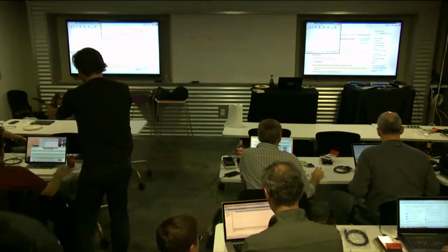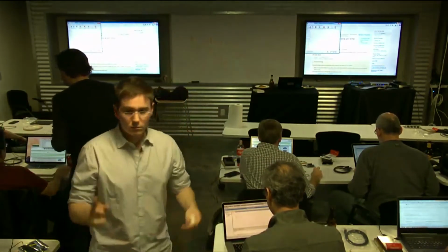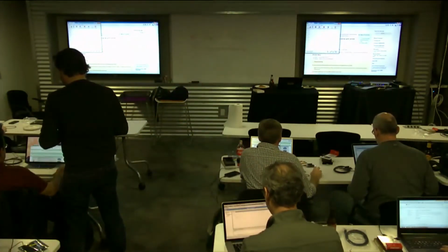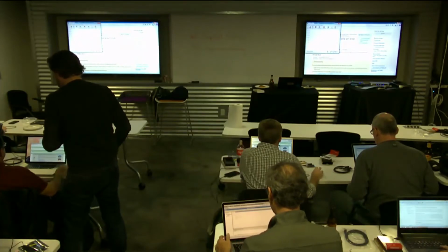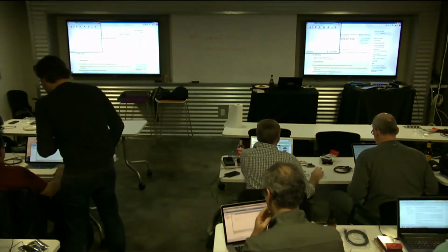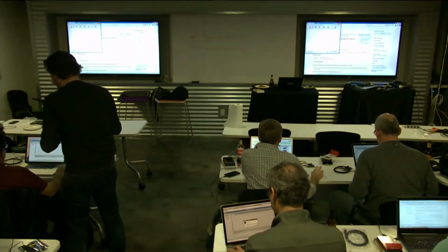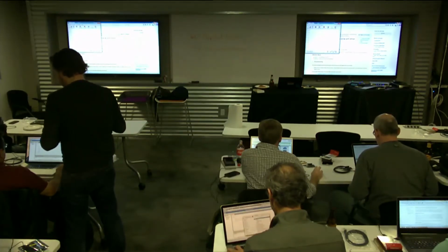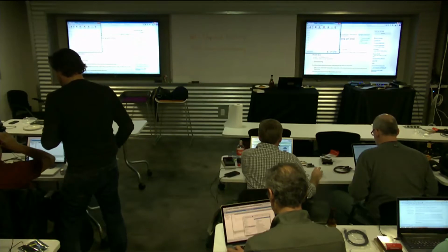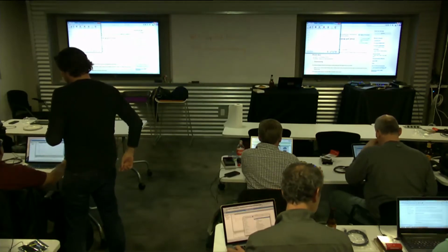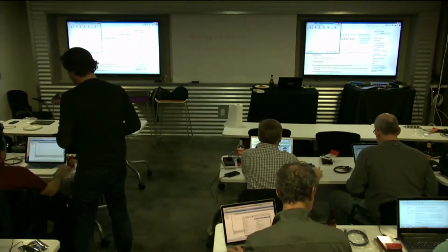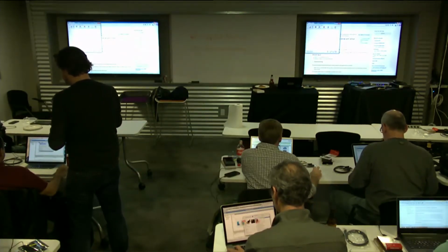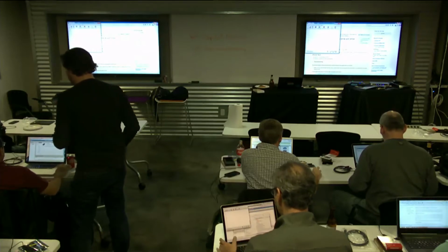If you want to change the baud rate, you have to actually create a serial object. So there's a peripheral called serial, and whatever name you want to give it. By default, it's USB TX and USB RX for the pins that automatically map. So it'll make a USB serial port and use that name. And then you'll have the option to say, whatever this object is, dot baud, give it the speed you want, and now all your messages pass off.